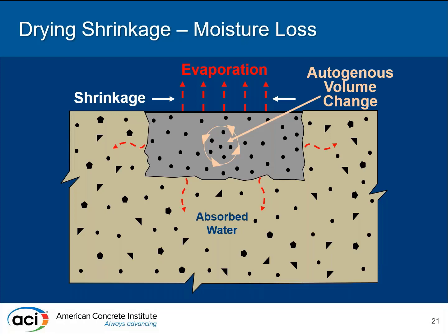Delving into that a little deeper, one of the first things we should think about when we talk about compatibility from this viewpoint is not strength, but drying shrinkage, really the volume change movement and how that's going to happen together. We need to realize that the repair material and the original material are going to have very, very different histories. All concrete shrinks.